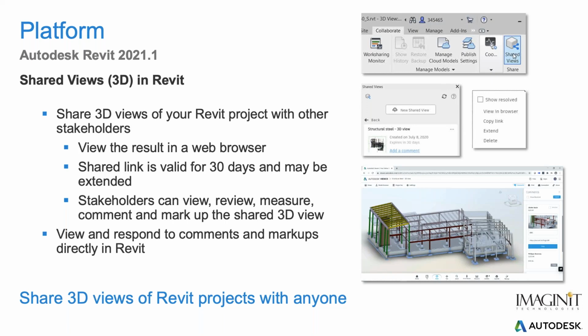And what's great about this feature is, when you share the view, whoever you send the view to can review, view, markup, measure, comment, all right there in the 3D view. And then you can actually refresh that view in Revit, and you can see those comments and markups, and you can respond directly to them right through Revit. You don't have to go look at that 3D view in the web browser. It's all just native to you in Revit.